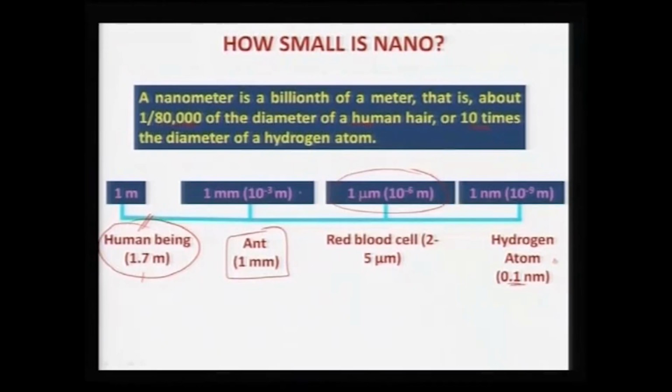And when we talk about a material, we find that a material has polycrystalline grains in it, and the grains extend to the order of a couple of micrometers. So, the grain size can vary from micron to submicron, and now we are worried about the microstructure of a material, and that approximates to the micrometer length scale.